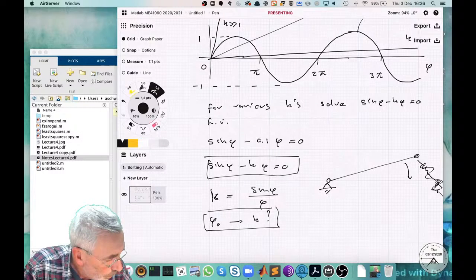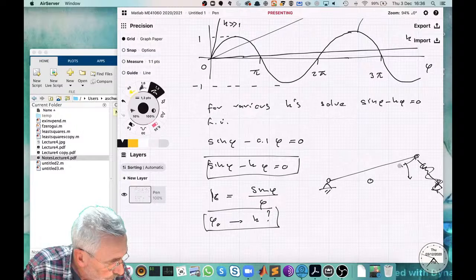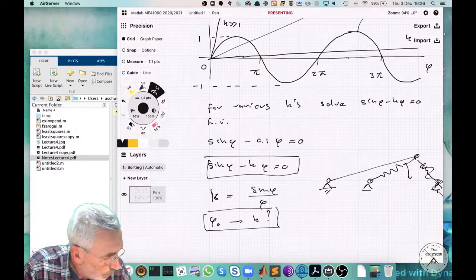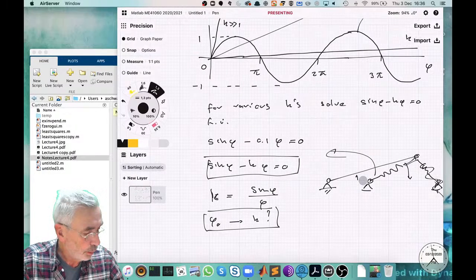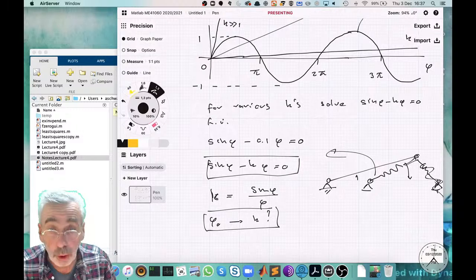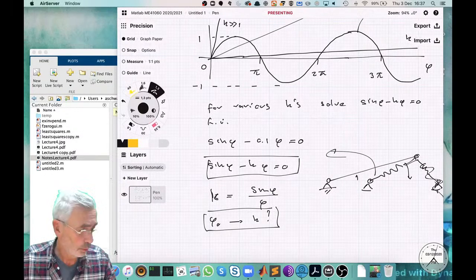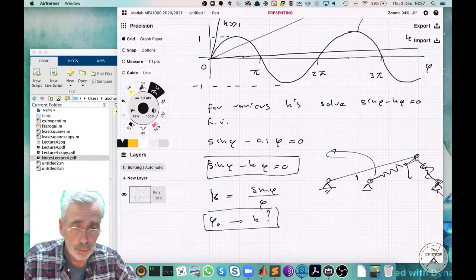However, if I put the spring here, then a small deviation of the bar will pop the thing out. So this is like a negative spring. So this is the way to make a negative spring. So yeah, negative springs do exist. That was the bottom line.